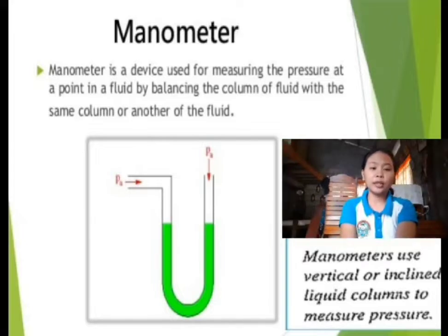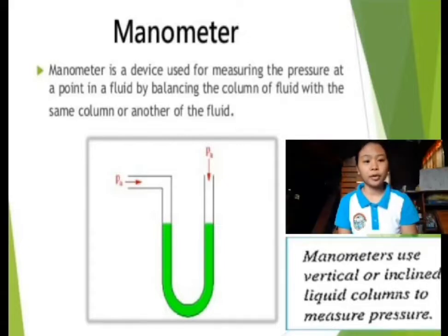And the manometer also consists of a transparent tube constructed in the form of an elongated U. And we can see in the picture of the manometer that it is a U-shaped tube of glass, filled with some liquid. And that liquid is typically mercury because of its high density. With the help of a manometer, we can measure comparatively high and negative pressure. And typical manometer applications also include measuring pipe fluid flows and gas pressure.